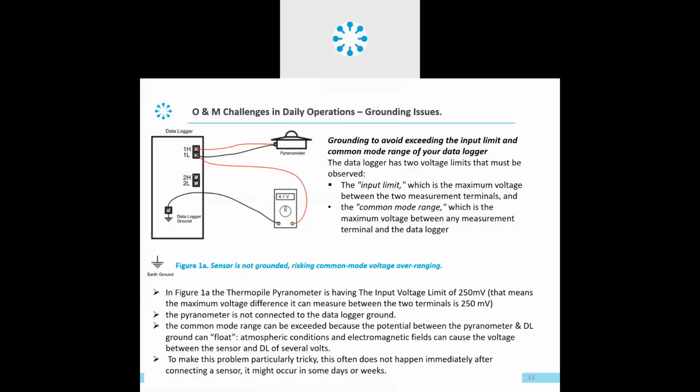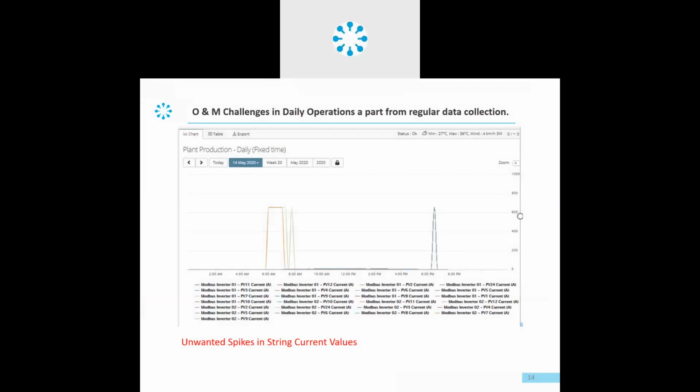These troubles I was talking about, these spikes or surges or damages, there is a big reason behind this. Of course, it could be EMI, EMC interferences, surge inductions, or loose connections, which might be creating unwanted spikes. But then there is another most important reason behind this, which we really used to ignore when it comes to the communication part, which is grounding.